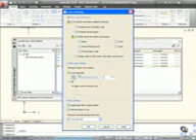Now, the other thing I'm going to look at here is the Isolate Layer Settings. You can lock and fade layers. So when the layer is locked, you can fade it so that you know it's locked. So I can do that there. I'm going to take that up to 75, like so. So the layer actually fades by 75% when you see it on the drawing as locked. So I'll OK that now.